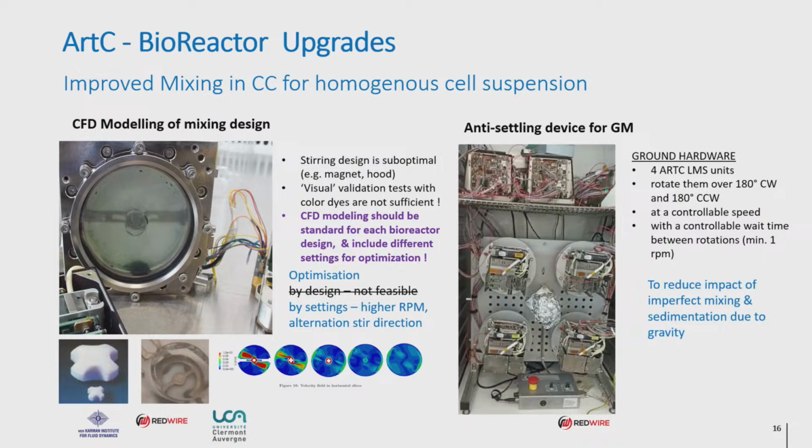While PD said, no, all the dye tests that we did show that we have perfect mixing in this setup, in this design. We pushed until we had additional people doing CFD modeling, and there it came out that indeed we have high fluxes close to the stirrer, but all the blue is actually dead zones because of these additions that were made to keep the stirrer bar in place. Of course, all of this came late, and the design cannot be changed anymore, but then we found solutions, workarounds, to have stirrers turning at times like this. Then it has a ramp up, a ramp down, it turns back, to still try to improve.